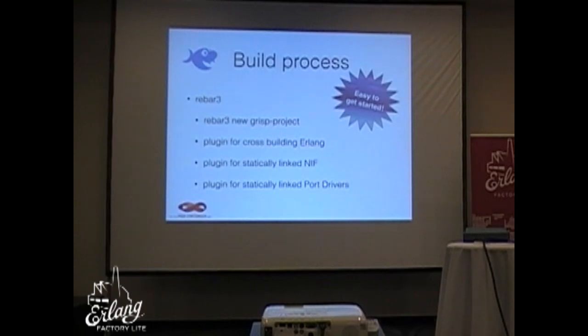So to make this even easier to get started, as I said before, we want to provide basically the tooling around all of this as well, not just open source some bunch of stuff and hope for the best. So we want to have rebar plugins for creating new Grisp projects out of the box, and for building Erlang, statically linking NIFs and port drivers. So if you just want to build a pure Erlang application, or let's say you're happy with the drivers that come out of the box that we provide, you're basically good to go.